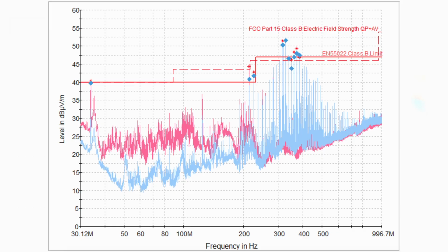Remember that with EMI, you are usually dealing with frequencies in the range of tens of megahertz all the way up to 1 gigahertz. So even a tiny amount of parasitic inductance can have a significant impact on your common mode emissions performance. The best way to minimize your ground plane impedance is to follow PCB design best practices. So doing things like using multiple ground planes where you can. And one super important thing that you need to do is avoid at all costs putting any slots in your ground plane.